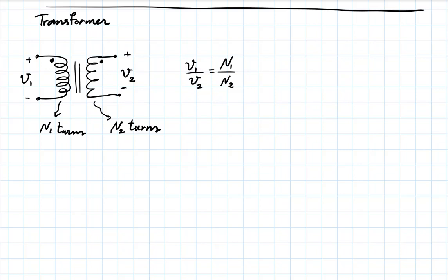So this would help with what you're asking about. You don't violate conservation of energy here, maybe unfortunately. Because the current on the output will be then correspondingly small. So the power at the input and output will be the same. Okay? So you go up in voltage, go down in current. So you have to have enough power capacity to get what you want. Yes. But this is something that you will see.